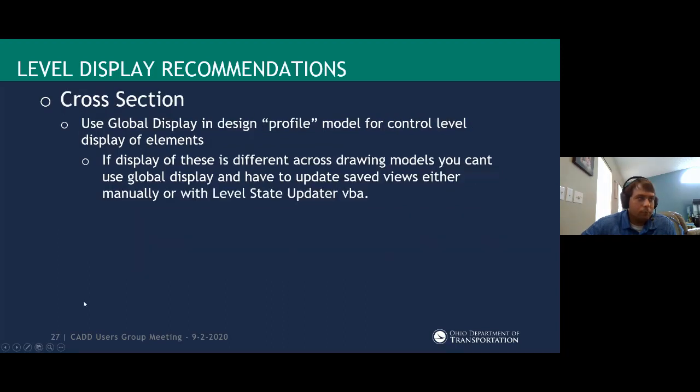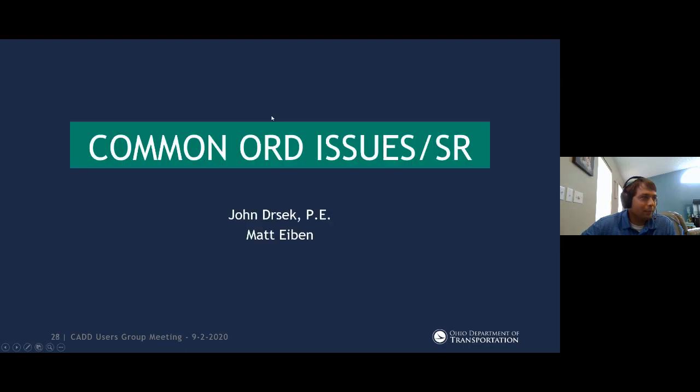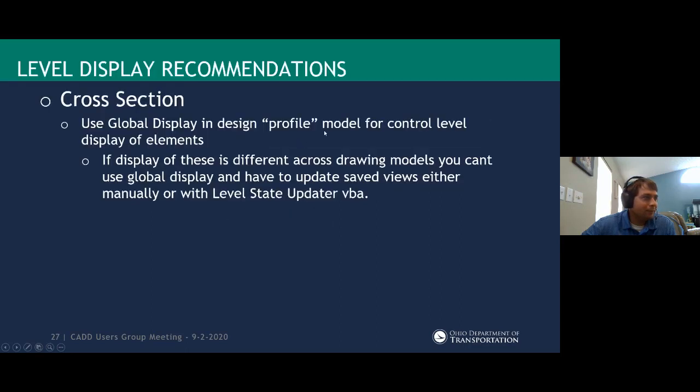Cross sections. Use global display. So here's a theme here, which I forgot to update that slide because it says profile model. So my bad there, but this one's a little simpler because you can't really do anything in the drawing model, right? They're all grayed out. So it's simpler in that aspect. So if you need to control it across the board, use global display.